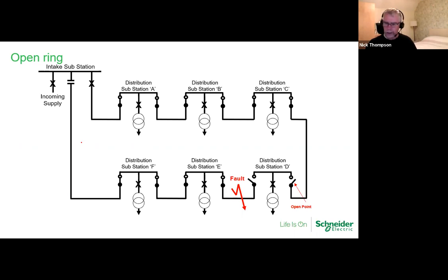So we know where it is, so we've worked out our switching schedule. This is just my sort of thoughts on this; in reality, it may be something slightly different. But we've got the left-hand ring switch on substation D now open. We can now safely close the right-hand ring switch on substation D. That's restored supply back to that transformer. Moving into substation E, we can then open the right-hand ring switch. That's now isolated it at both sides.